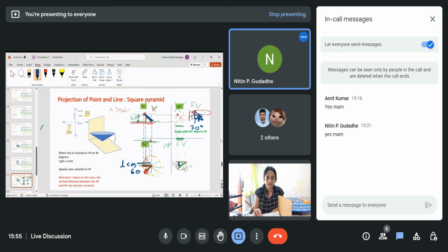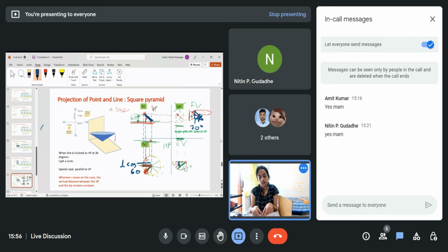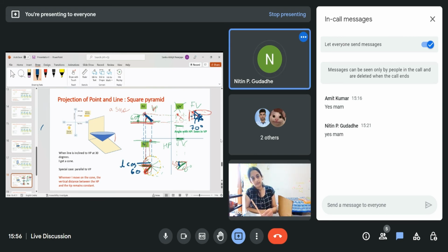No, no. Why? Angles are different because first we are rotating with 45 degree, then 60 degree. But here also, I rotated with 60 with respect to HP. Here with VP, after rotating with 60, I'm rotating by 45. Keeping the point same, first I'll do 45 only. Here also I did 45. I'll again do 45 and then go 60. Yes, then we can reach the same position.